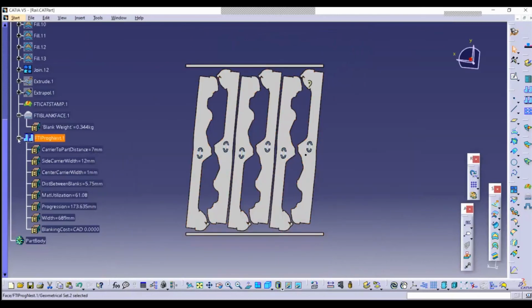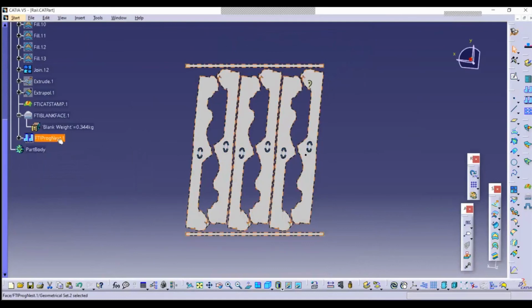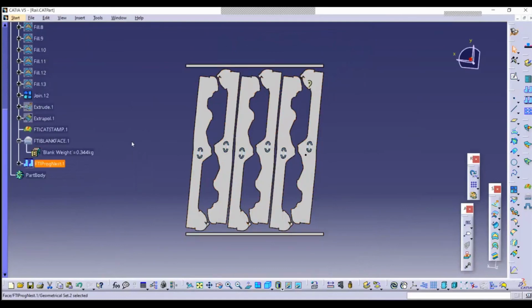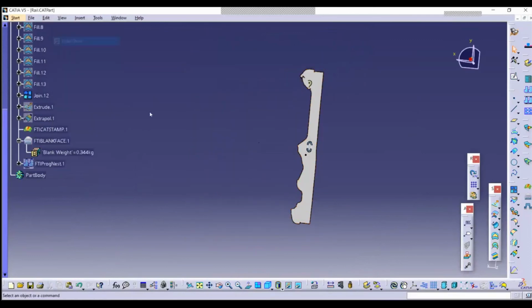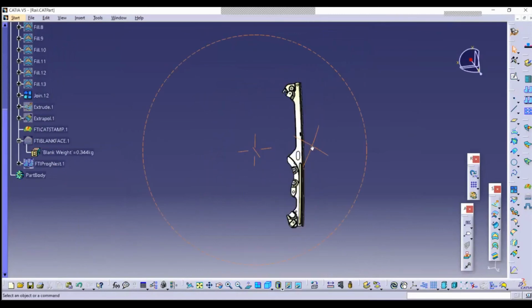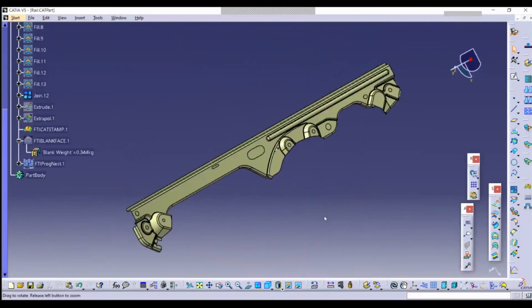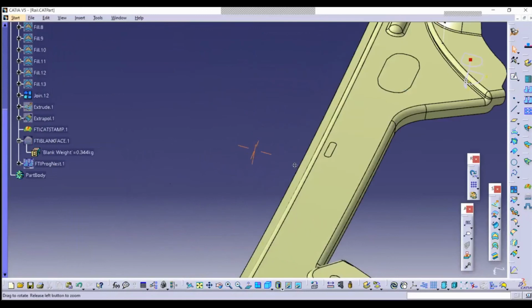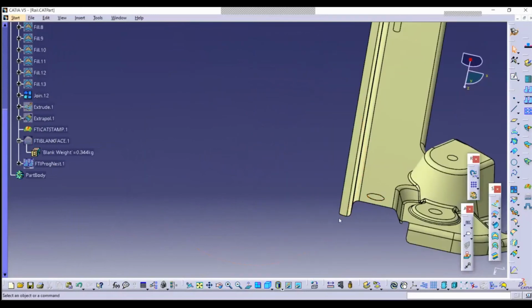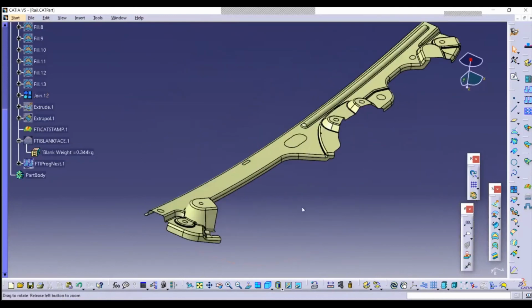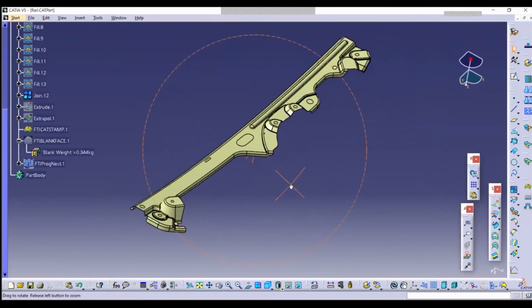So the other thing that I was alluding to was the ability to do double attached. So the way that we would do double attached is, again, we would have to do some manipulations to the existing geometry. So we would have to take this geometry and we would have to create a plane. We would have to split. So we would go through the process of splitting the surface as well as mapping this edge and then mirroring it. Because of the time that we're at right now, it looks like we're about a quarter to the hour.